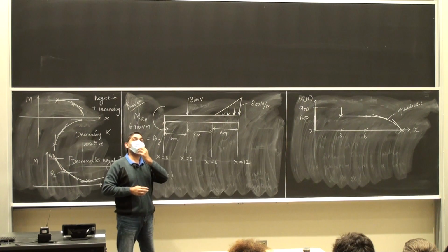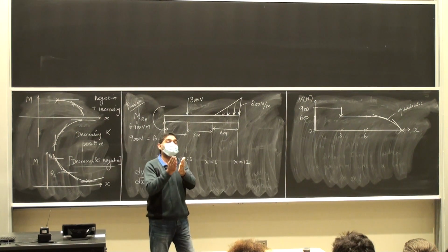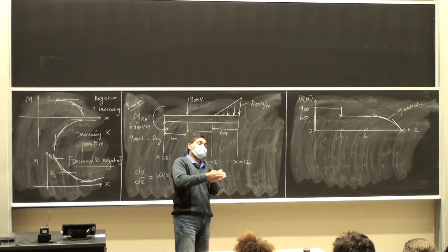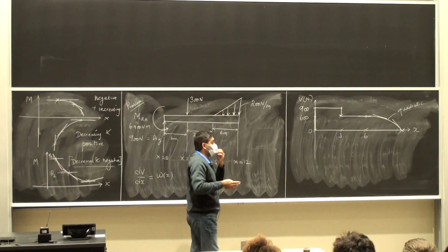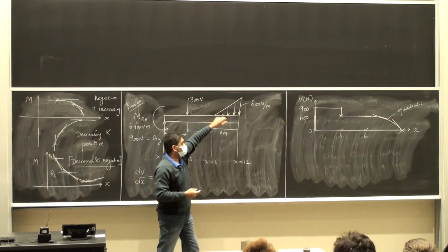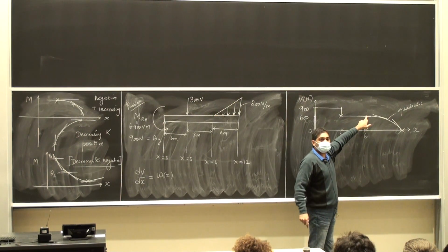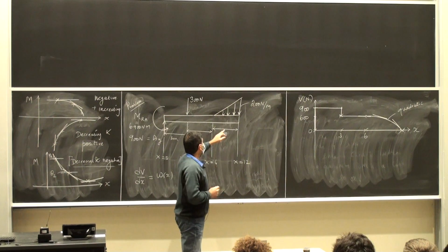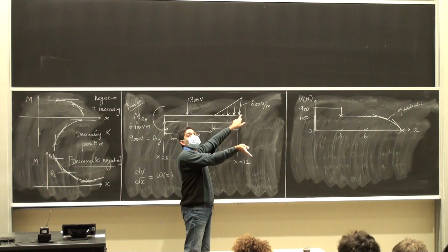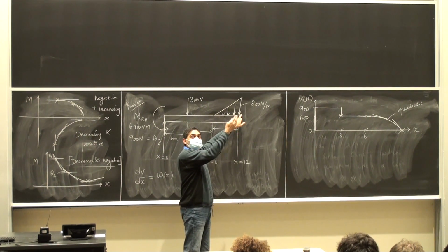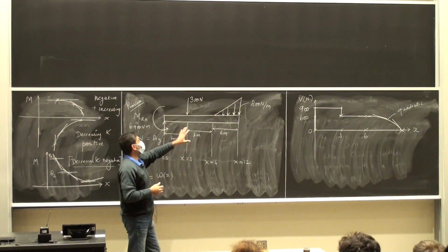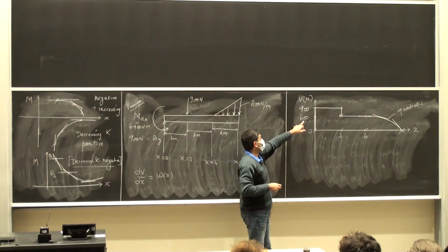Then suddenly I see that there is a distributed load. If you have a distributed load, it will gently take you home or gently take you somewhere else. How do you go from where to where? From here to there is by looking at the intensity of the load distribution for the shear force diagram. It starts at 0, so my slope starts at 0 here. My slope increases because the intensity of the load distribution increases, but the slope itself is negative. So I'm going to go from 600 newtons all the way to 0. How do I know that I'm going to 0? The area of this guy should be equal to the magnitude of 600 newtons.